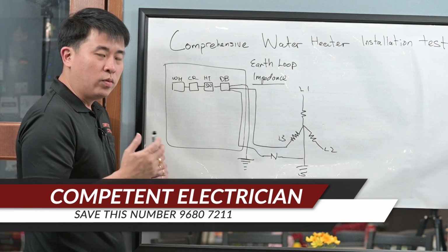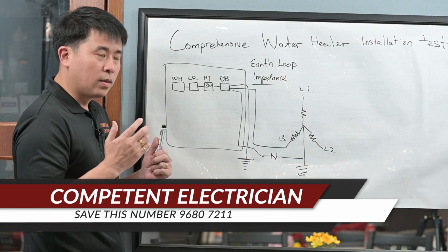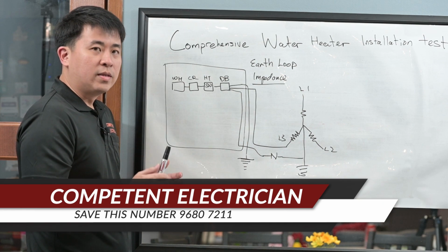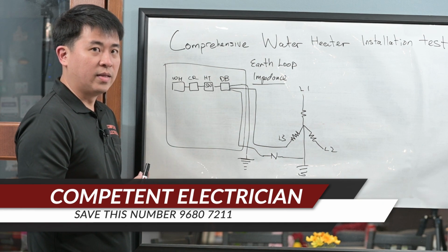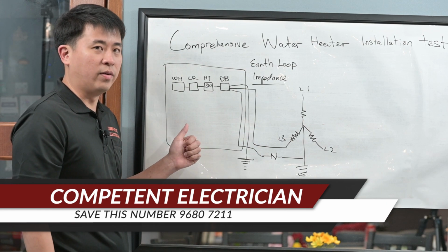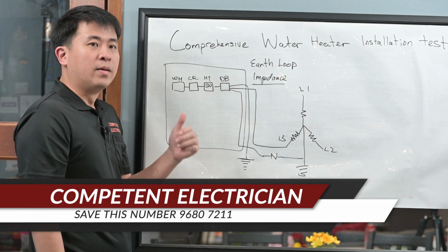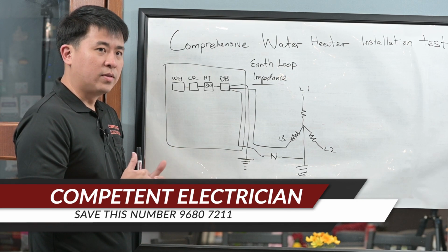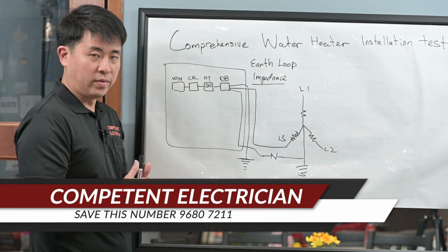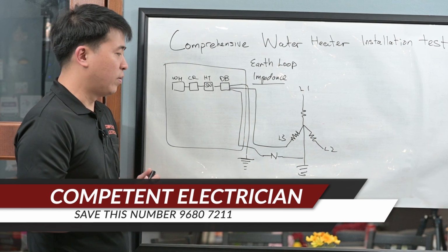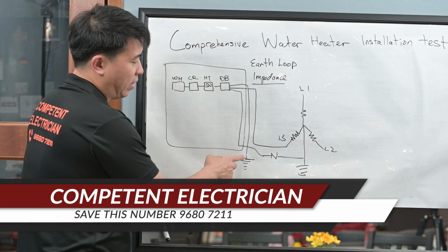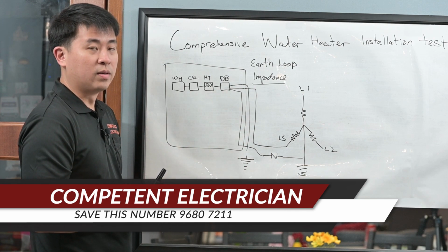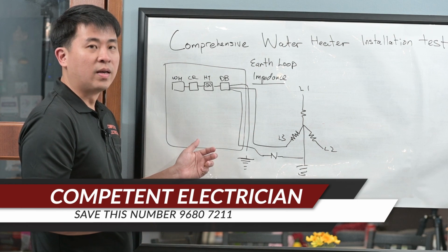Why do you need to do this? Right. About 9 months to 1 year ago, we had a resident call us from a particular condo, and they said that they can feel electrical current on the iron grill. That means the metal gate, even the lift lobby, and some of the metallic parts of the house. And we find that it's very unusual, right? So we went to attend to them, and do you know what we found? We found there's a broken cable, right? There's a broken cable between the bonding, the main water pipe bonding and the main earth.